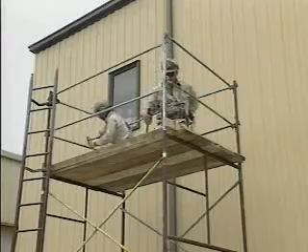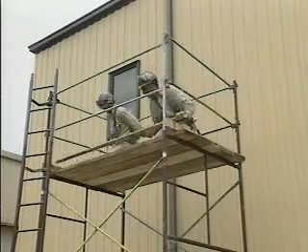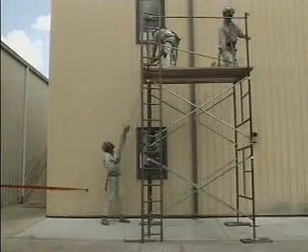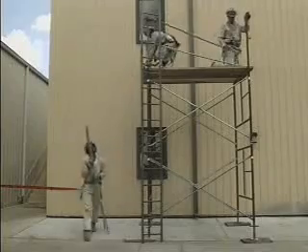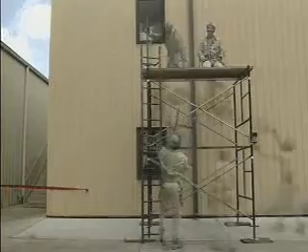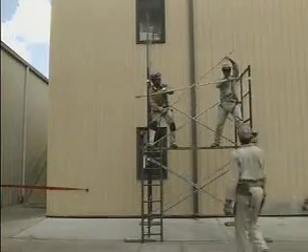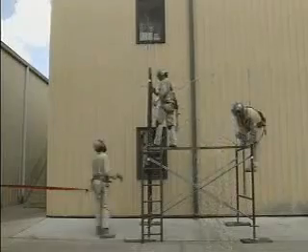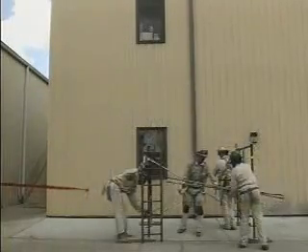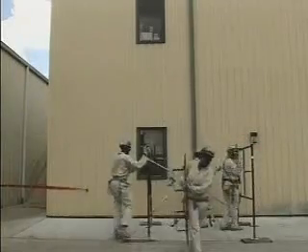After the green tag is removed to indicate that the scaffold is unsafe for workers, the toe boards are removed from around the scaffold flooring. Then the upper and middle guardrails are removed, along with the guardrail posts. The upper sections of the ladder are then disconnected, and the scaffold flooring is removed. Then the upper cross braces are taken off, and the upper end frames are lifted off of the lower end frames. The lower cross braces are removed next, along with the last section of ladder.